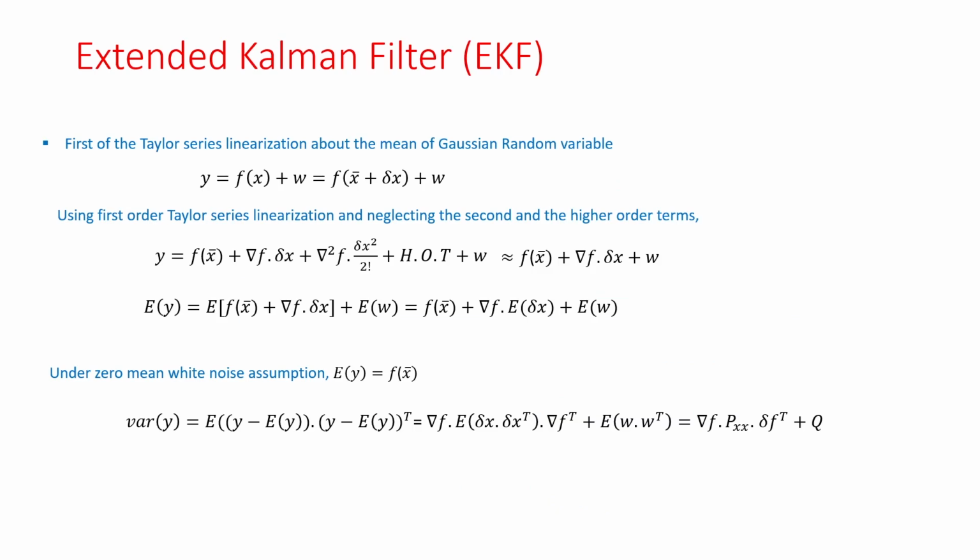Now, coming back to the extended Kalman filter. What is called extended? Kalman filter, you know, is an observer that estimates the states of your system. The system dynamics is also corrupted with white Gaussian noise, using some measurements. That measurement system is also corrupted with zero mean white Gaussian noise, and it tries to estimate the system. Fine. Whatever in control system terminology is the Luenberger observer, it does the same thing as a stochastic observer or optimal observer. That is all the Kalman filter is.